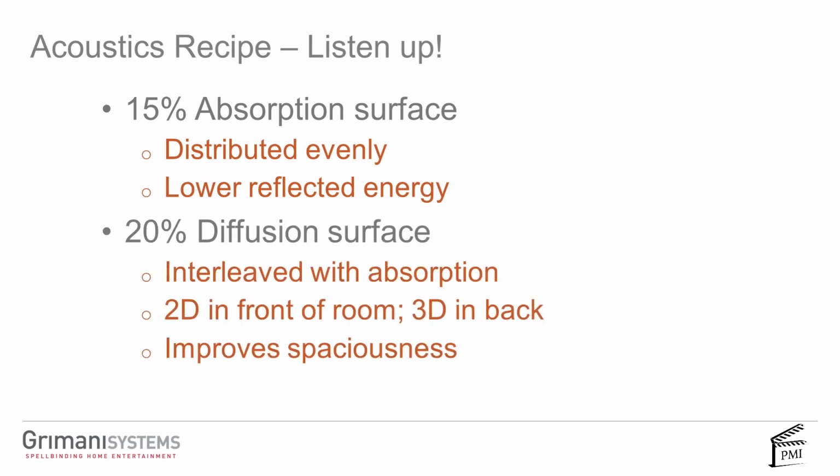The other thing you want is about 15% of scattering surfaces. I use the word diffusion, but really the true term should be scattering, which is surfaces that have broken shapes. There are lots of purpose-made materials from lots of different vendors. I'll show you a bunch of pictures later.